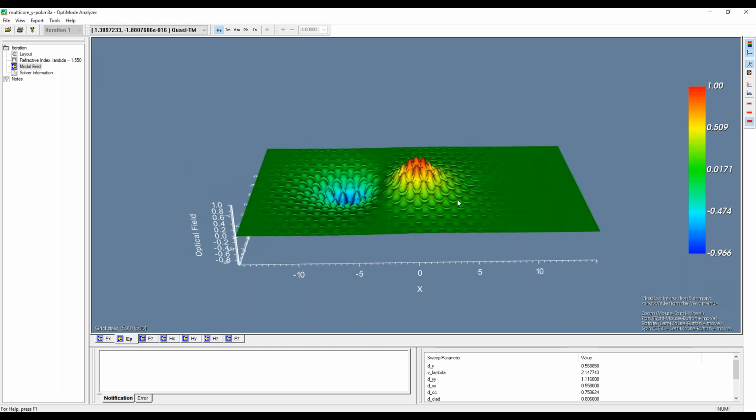Not a lot of the power is propagating in the X core. And then of course, the same way to find the coupling length of the structure for the Y polarization, you take the difference of these modal indices and plug them into that equation. It's very simple, and you'll get a coupling length of about 630 or 640 microns, I believe.